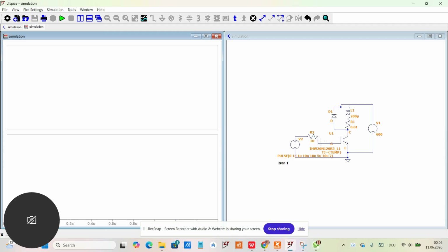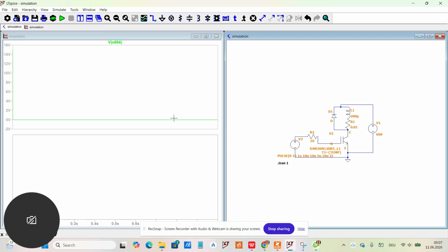So now let's look at the voltage, the pulse that is going to the gate. First I will left click here at the point where I want to place all my voltages, at this upper pane, and then I bring my mouse to the gate. I click at any point on this schematic, and then I bring my probe where I want to measure the voltage. When it touches the line, I click, and there we can see, since it is a double pulse, I've set it at a very high frequency of about 100 kilohertz. So you need to come here and zoom.